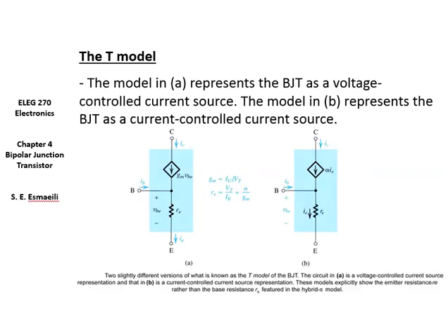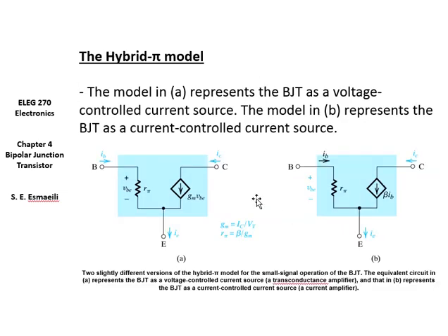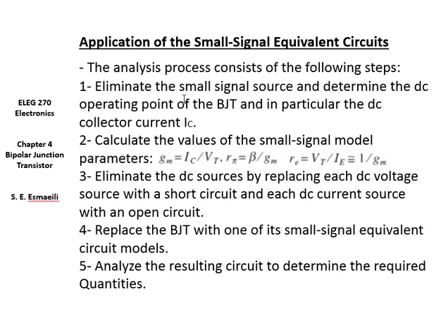You also have the option to use another model called the T model, but I recommend you to stick to the pi model, which is very easy to deal with. And I have summarized for you at the end how to analyze a transistor circuit in AC.